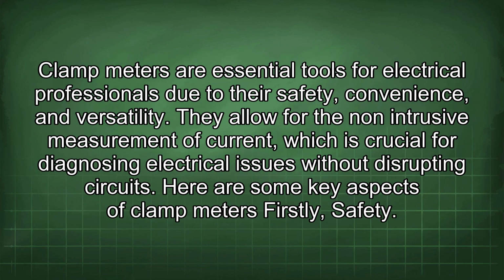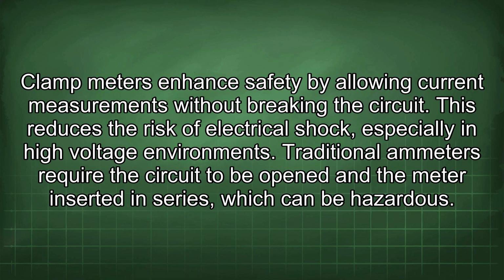Clamp meters are essential tools for electrical professionals due to their safety, convenience, and versatility. They allow for the non-intrusive measurement of current, which is crucial for diagnosing electrical issues without disrupting circuits. Here are some key aspects of clamp meters. Firstly, safety. Clamp meters enhance safety by allowing current measurements without breaking the circuit. This reduces the risk of electrical shock, especially in high-voltage environments. Traditional ammeters require the circuit to be opened and the meter inserted in series, which can be hazardous.